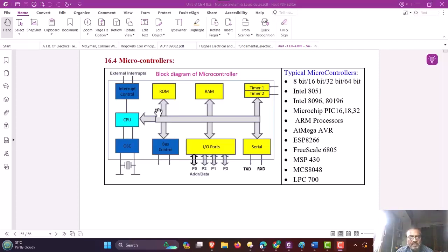Whereas in a general purpose microcomputer system, these peripherals are externally connected and implemented. So, a general purpose microprocessor doesn't have support for these peripheral devices on chip. They have the facility to connect these peripherals via the interface of address bus, data bus and control bus pins available.